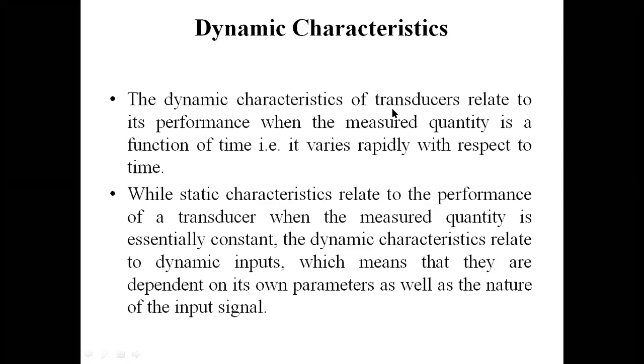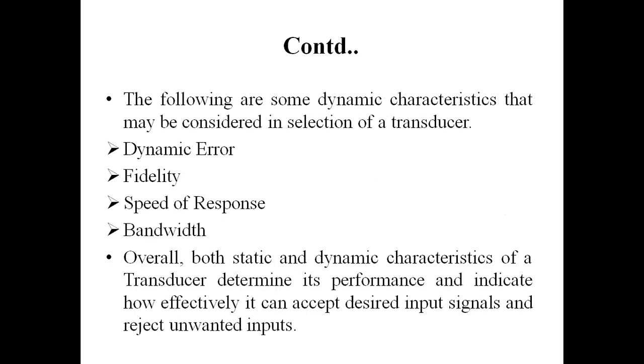While the static characteristics relate to the performance of the transducer when the measured quantity is essentially constant, the dynamic characteristics relate to dynamic input, which means that they depend on the system's own parameters as well as the nature of the input signal overall. Okay. So here we have dynamic error, fidelity, speed of response, and bandwidth. These are all the dynamic characteristics.